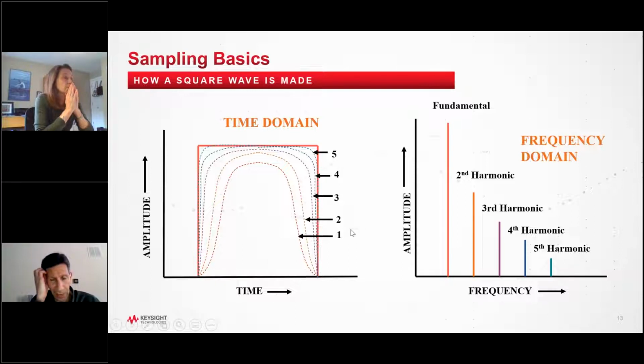you can see from the slide what we generally recommend, is that if you're looking at a signal with a fundamental frequency, we should be able to capture the fifth harmonic. The closer you get to the fifth harmonic, you'll get closer to the actual shape of the signal that you're looking at. And you can see it gets better and better as you go from first harmonic up to the fifth. And by the fifth, you pretty much get a good representation of the signal.